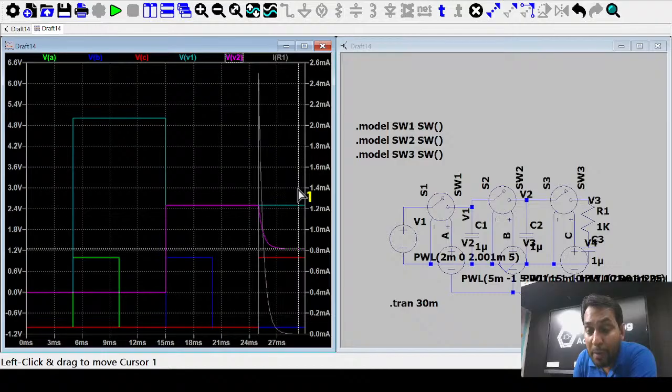In the previous case, the capacitor discharges suddenly, or I can say rapidly, from 2.5 to 1.25, because the resistance is not present and the current is very large. But in this case you have a resistance, so the resistance will limit the current, and it will not allow sudden or rapid changes in the capacitor voltage.